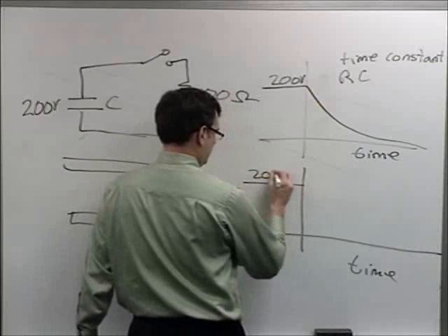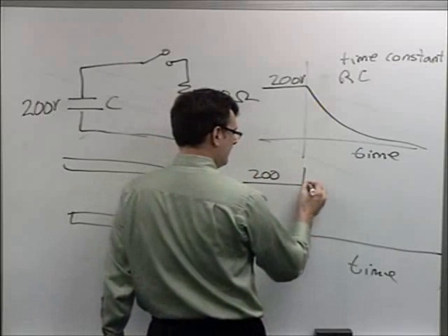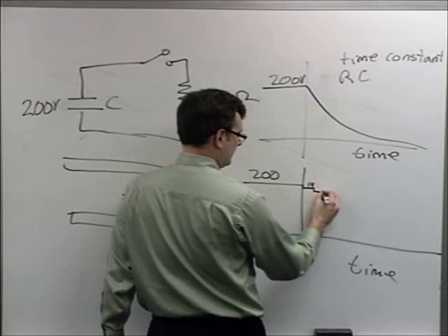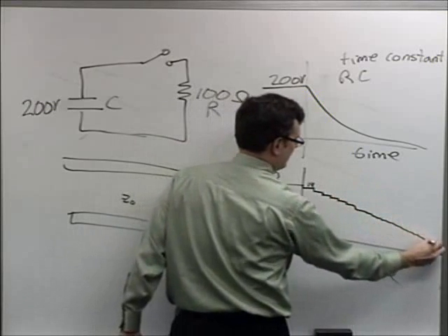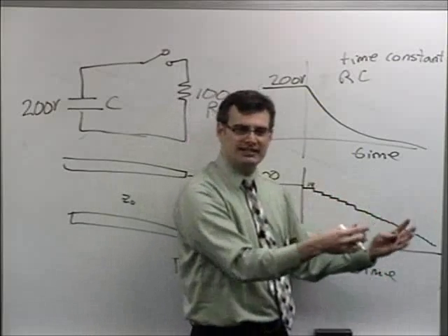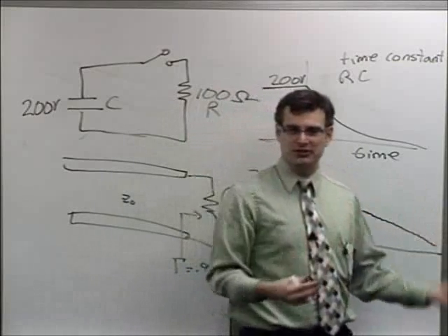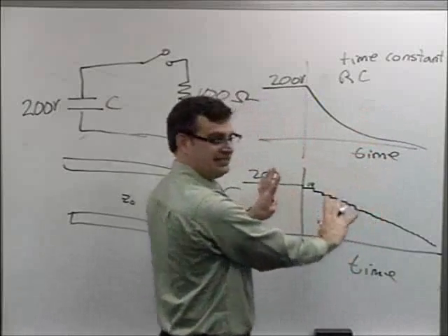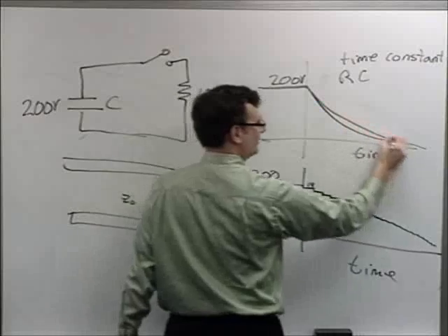200 volts. That very suddenly, and for a short period of time, 2 transit times to be exact, becomes 190 something volts. And then a little bit later it becomes 190, a little bit less volts, and so forth. And you stair step down over time, and what you find is that that's geometrical decay, right? Every 2 transit times I lose the same fraction of a voltage. So what I actually get is a geometrical series, which if you stack those stair steps together, and step back and look at it at a different time scale, looks like an exponential.